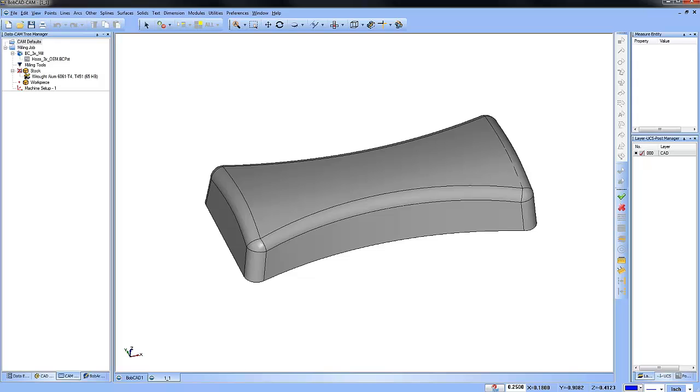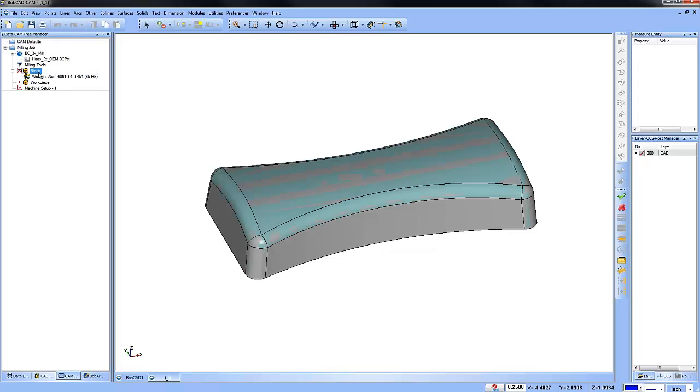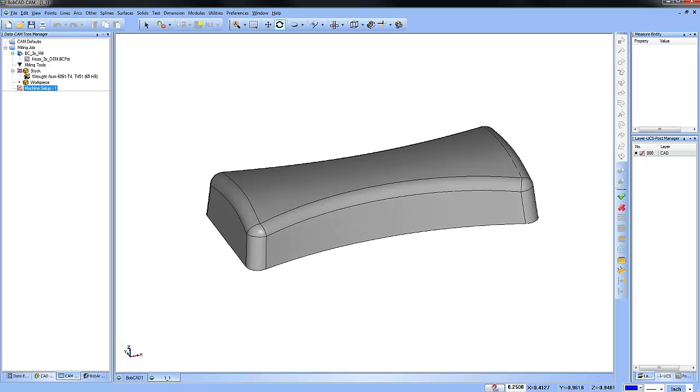All right, so the first one we're going to look at is the planar toolpath. So everybody's on the same page, I already have the job set up here. I have my stock selected as the part model, and I have my 0 set to the bottom of the part. That doesn't really matter. I have some material chosen, and we're ready to start loading in our toolpaths.